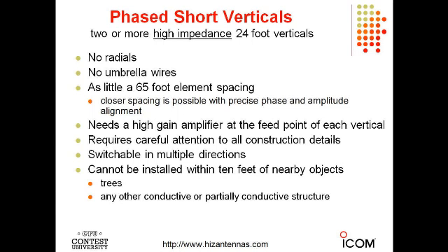But you can purchase the antenna that has the high gain amplifiers that are matched. But there's also some bad news. When you have lightning strikes and other things, it changes the characteristics of the amplifiers. So sometimes you might have to go back and test the amplifiers anyway to see if they're still working the way they were originally.